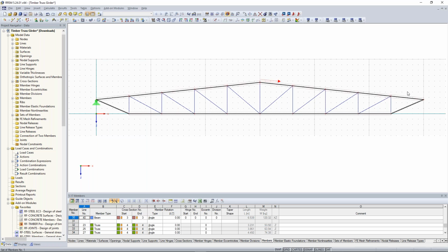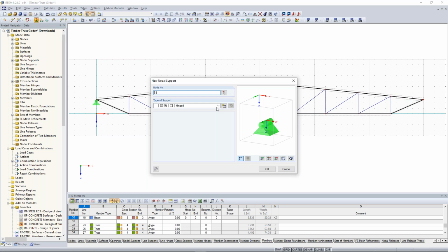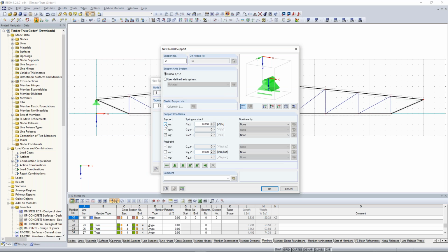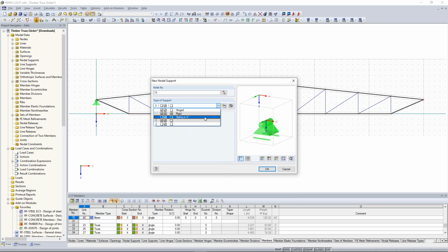And on the right side, we have another support, and this should be a support which carries only vertical forces. So I move this with this selection here on UX away, so that we just activate here the vertical forces. Similar to this sliding in X direction.